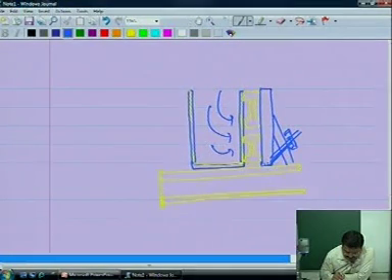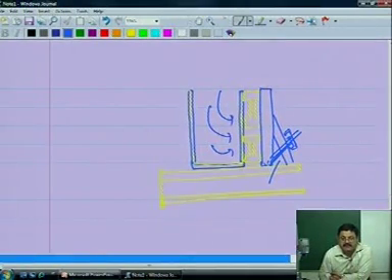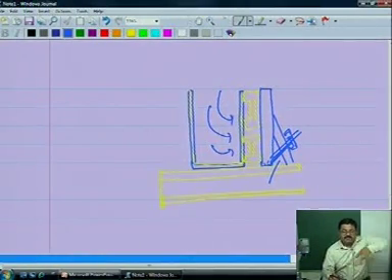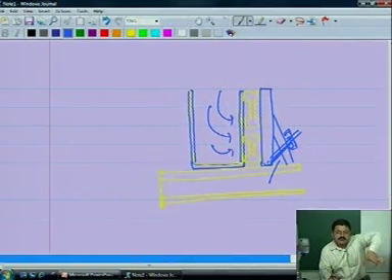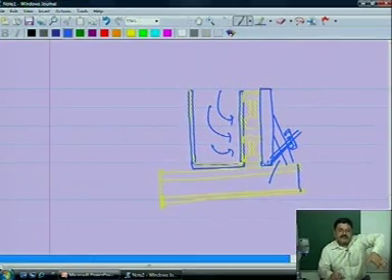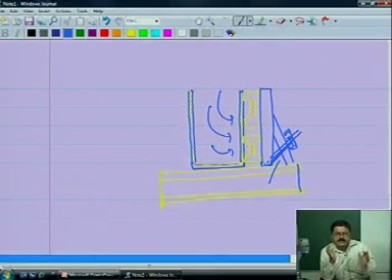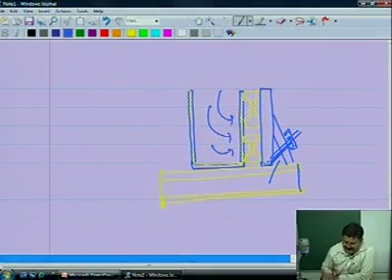So this H beam and this are connected together with the help of a clamp. It holds the flange of the H20 beams, and then you tighten the screw so that the lateral pressure is taken care of. Can you understand this?